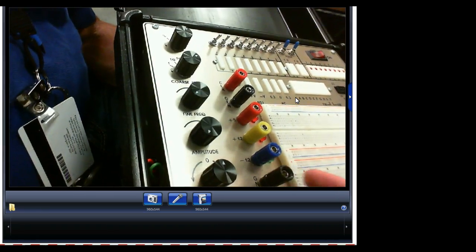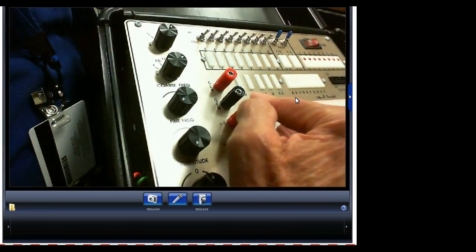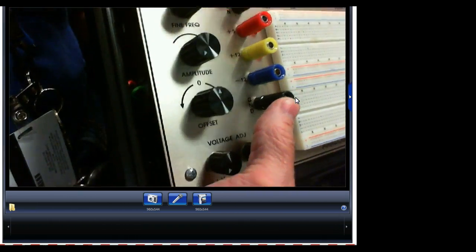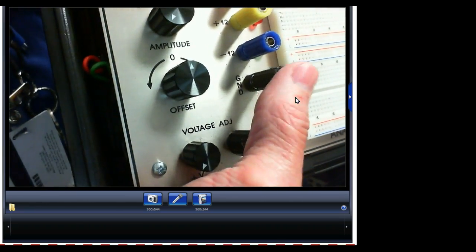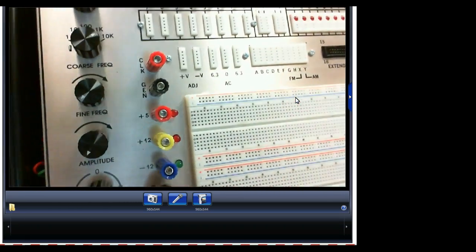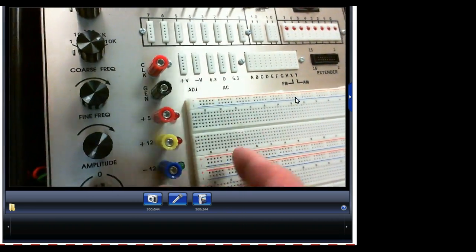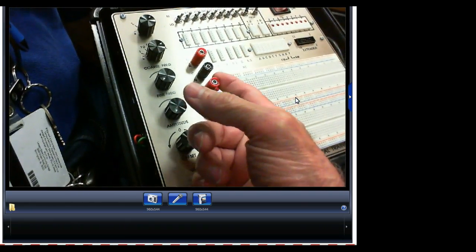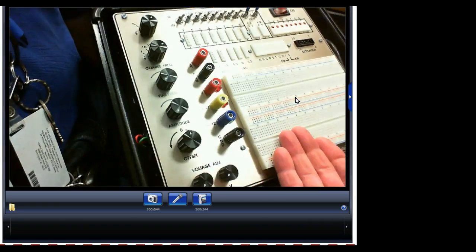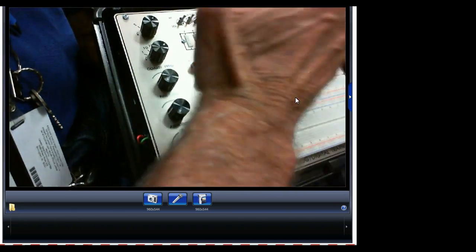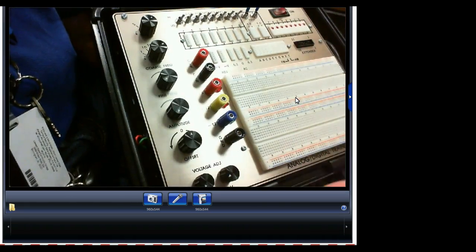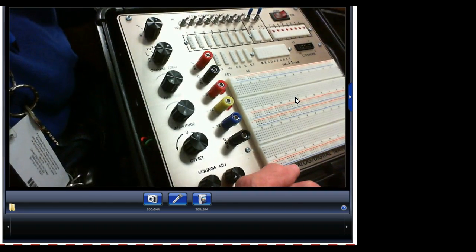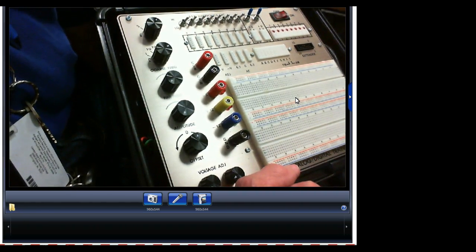And so if I wanted to measure the voltage on this supply, I would go between the black one, which is ground, and this is grounded, guys, so it's grounded to the power cord. And then there's 5 volts right there. So this is the one that we're using in the first lab. So we're using ground and 5 volts, and then we're going to connect it up to a potentiometer, right? So that way we can get any voltage, because we've got to start out across our diode at about 450 millivolts or something like that. So most of y'all had your circuit hooked up okay when we left.